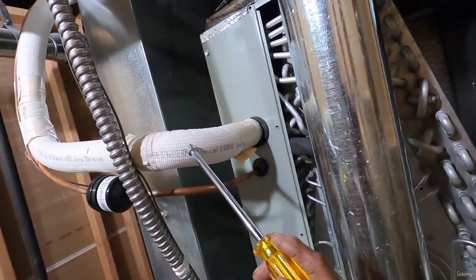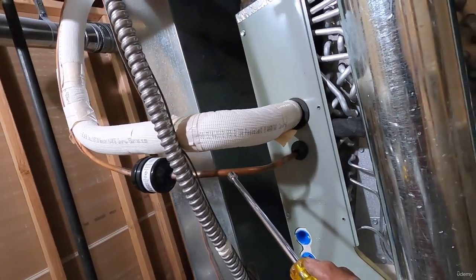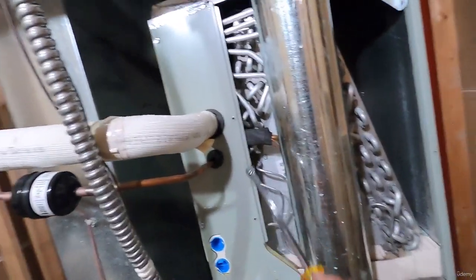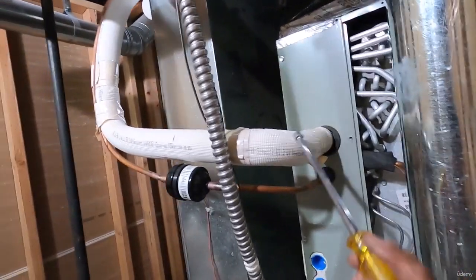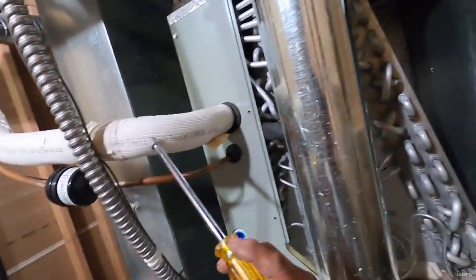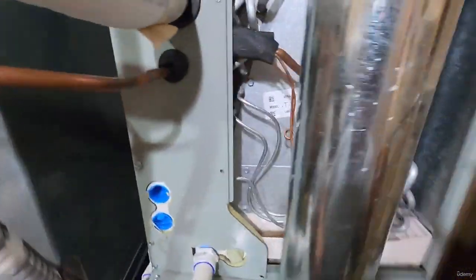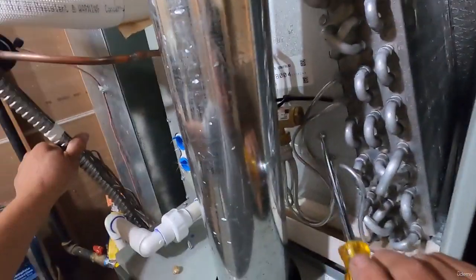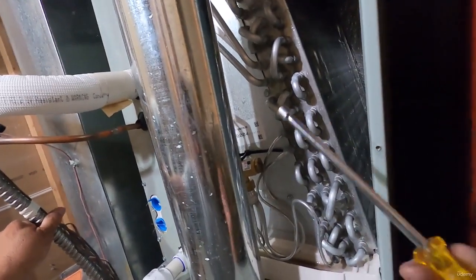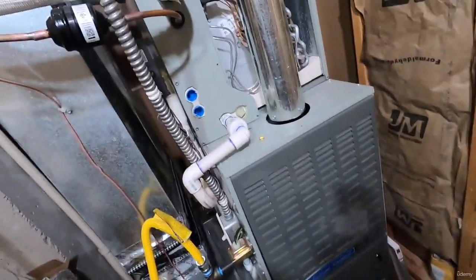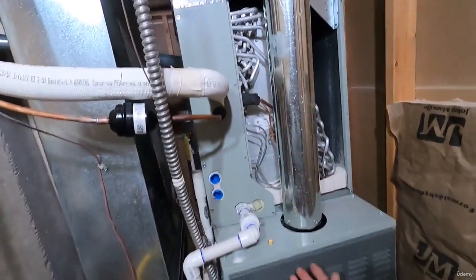low side. So it'll be a high pressure liquid on the high side, and then when it gets through and coming out of the evaporator, that's going to be a low pressure vapor. Okay, and that's the function of this expansion valve. And behind these plates, you'll see the underbelly of the coil, and that is where the fan of the furnace, the blower fan, will blow that air up through it.